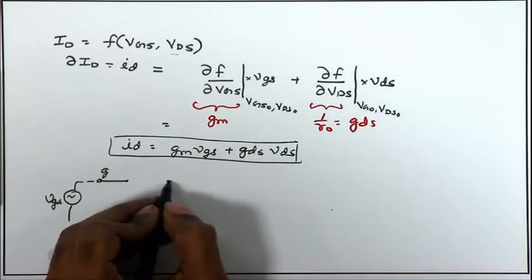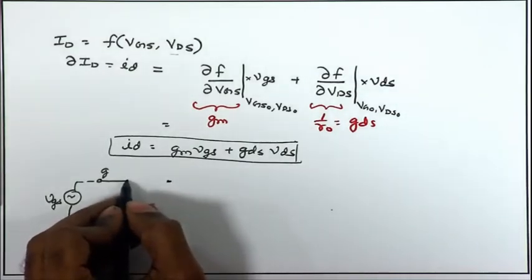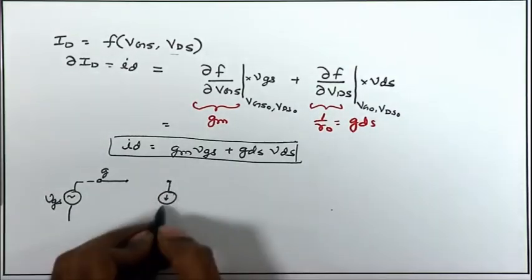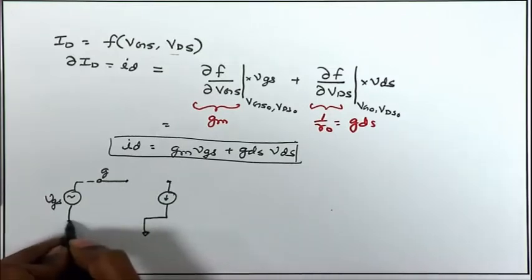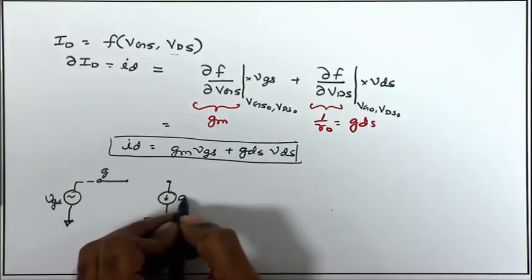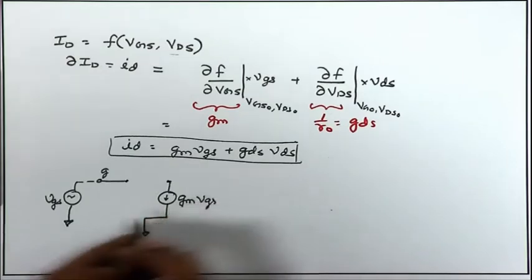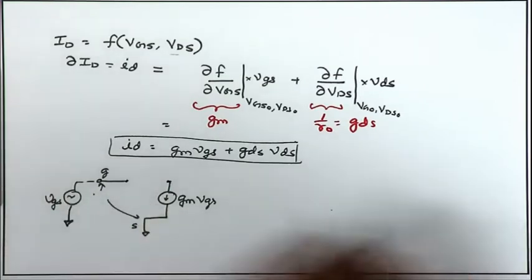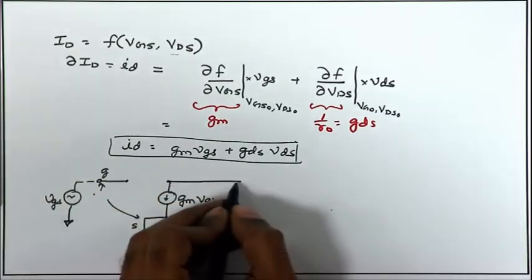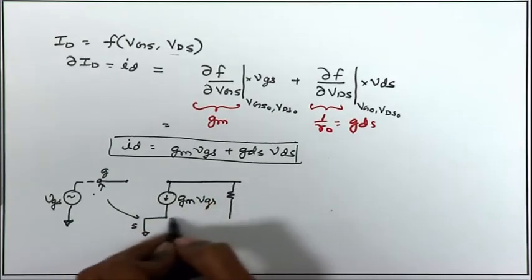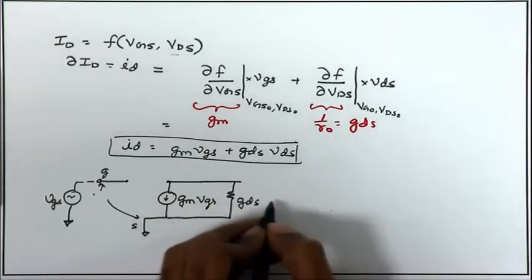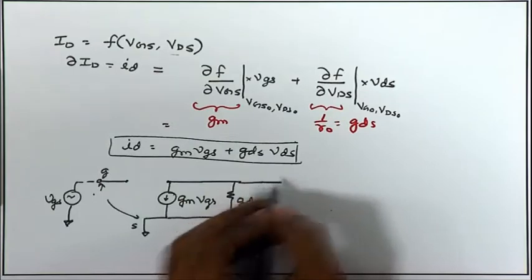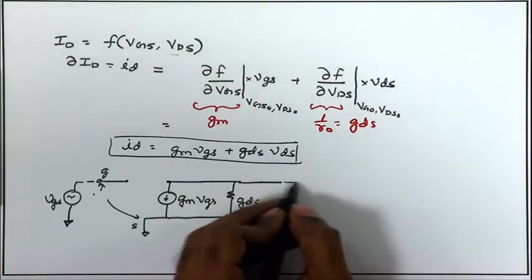Between the drain and the gate you do not have any physical connection ideally, because it is isolated using an oxide, and then you have a small signal current flowing between the source and the drain, that is Gm times VGS, because of the signal appearing between the gate and the source. Likewise, I have another conductance term, I can call it GDS, or effectively this GDS is the conductance term which is equal to 1 upon Rho, and that captures the effect of